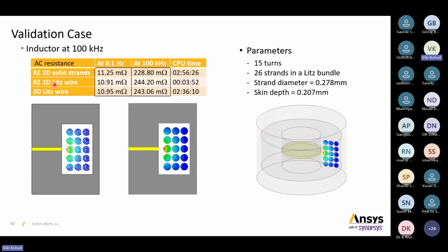And now you can simulate. Why do we use 2D first? Because 2D gets the results faster than 3D. So first we have to do the 2D. Then we optimize our design in the 2D section itself, then we can proceed to 3D. If the case needs to be validated, then you proceed to the 3D simulation case and then the validation.